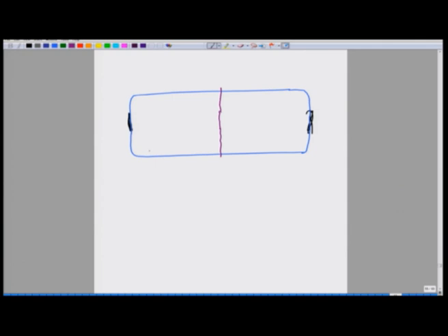and one side is p side. So, you will have lots of holes here, because you have put those acceptor impurities which have created energy levels, quantum states slightly above the valence band, and then those valence band electrons have gone to those impurity levels, creating lots of holes, and some electrons are still there.